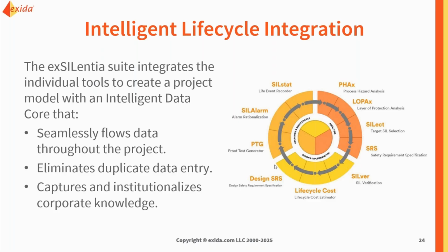And then if you wish to do a life cycle cost, you could do the life cycle costing for the SIS. And then this information gets built into the design SRS, which will be used to actually create the system. There's a proof test generator module, which will look at the SIS and what specific components you've used and create a proof test based on that.